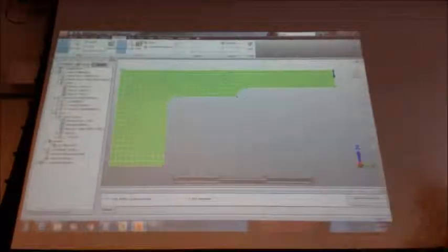And let's see, if you completely constrain the bottom and make it fixed, I don't think that's completely appropriate, because this is part of a larger device and we're just looking at a portion of it. So it does affect the deflection. It doesn't affect the stress really, but it does affect the amount of deflection. A potentially more appropriate way to constrain this is to prevent it from translating in the Z, because it's attached to another body, so it's not going to translate in that direction.